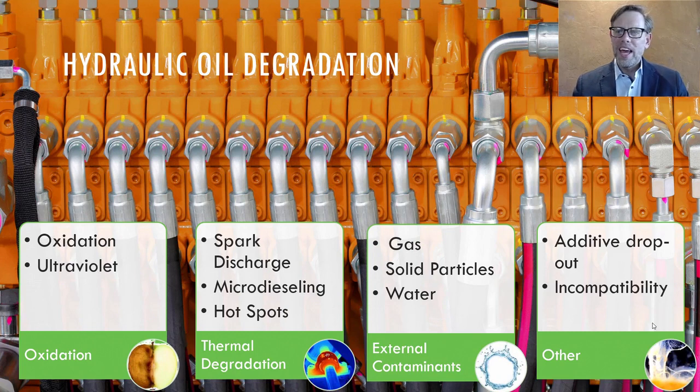And then finally, in some cases we've seen additive dropouts, and the biggest challenge that we have seen of late is compatibility. So if you are mixing, say, a synthetic oil on top of a mineral oil, some synthetics and mineral oils do not play well together, and even some mineral oils and mineral oils do not play well together. So don't assume when you put two different products together, you will have full compatibility, and that's something to be aware of as well, the result of which certainly can be oil-derived deposits.